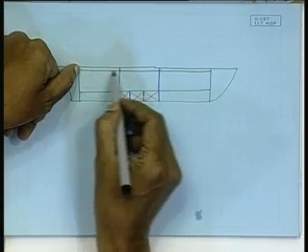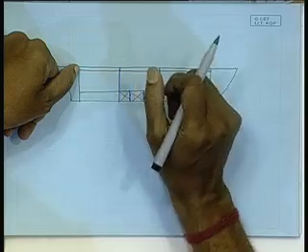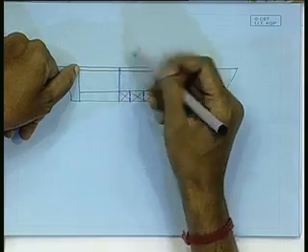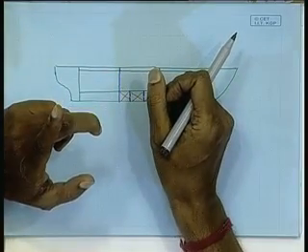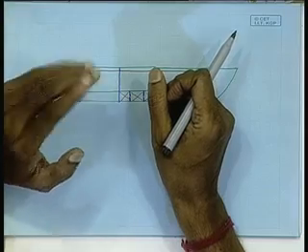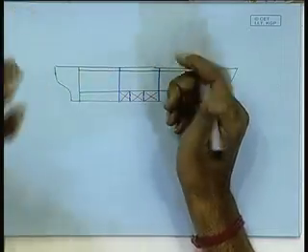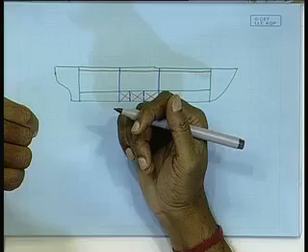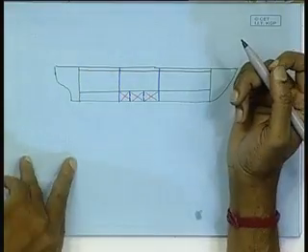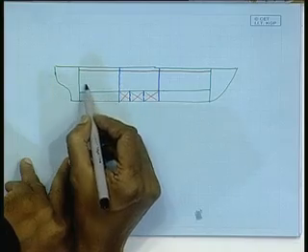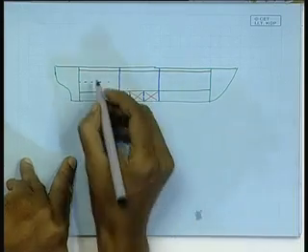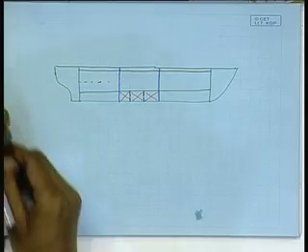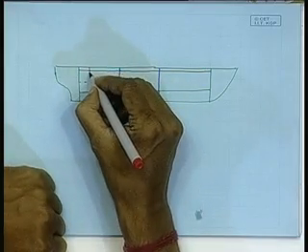So the span of the longitudinal will be this much, and you know the bending moment goes as the square of the span, right. So for a given loading, if this is my span, the bending moment on the longitudinal will be very huge. To keep the stress within the limit, the section modulus of the longitudinal will be very huge. That is not a very wise thing to do, because then the depth of the longitudinal may come up to this, isn't it? So what is done? You will have to have transverse members which will provide additional support.